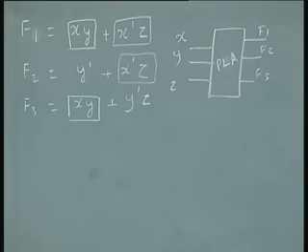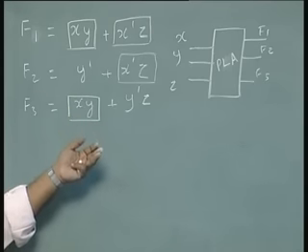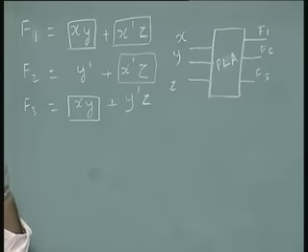How did I get it? In this case, as I said, the function was given to me. It could have been simplified, or sometimes you may have to be careful in simplifying it yourself. You do not oversimplify. In the traditional Karnaugh map approach, the aim is to simplify to the minimum possible form, so as to use the minimum number of AND gates, the minimum number of OR gates and the minimum number of inverters.